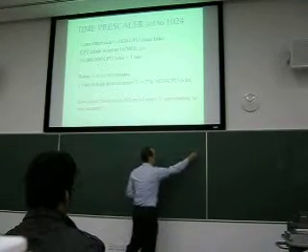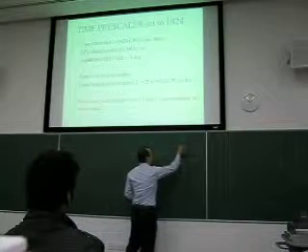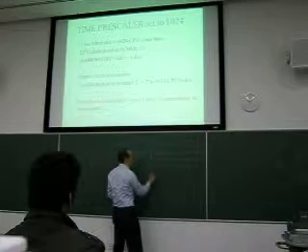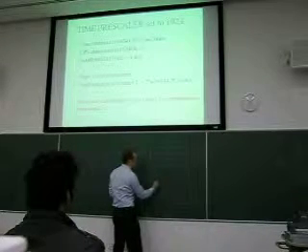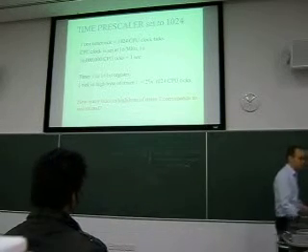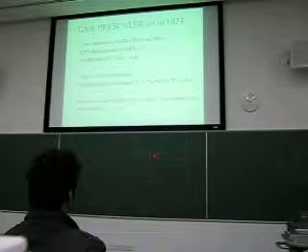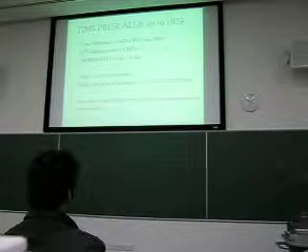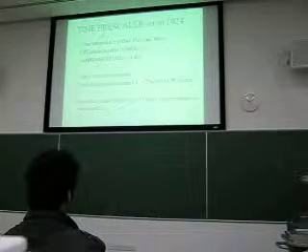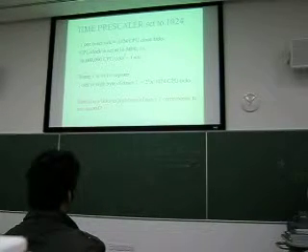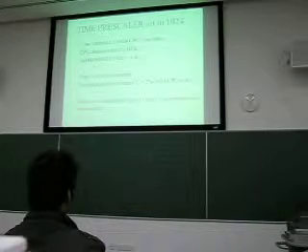Because I think this is 0, 1, 2, 3, 4, 5, 6, 7, 8, and 2 to the power of 8 is 256, I think. Yeah? So which means that 1 tick in the higher byte corresponds to so many CPU ticks. Everyone understand this bit? Yeah?